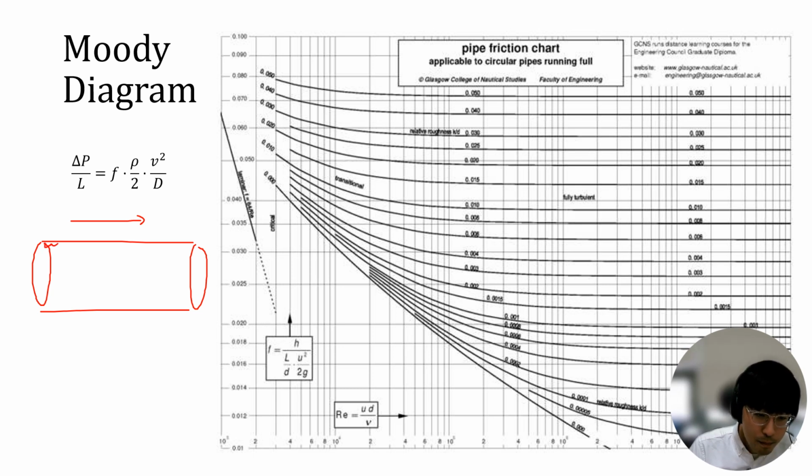They have a bit of undulation depending on how they process it, and also depending on their material, they might have a little bit of roughness on the surface. Let's say the roughness is epsilon here. The average roughness on the boundary is going to be epsilon, and the diameter is going to be d.